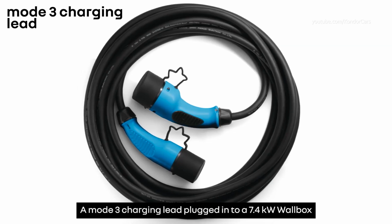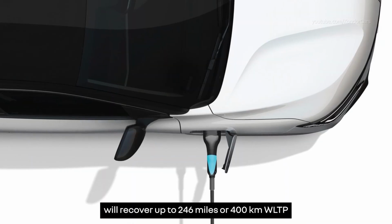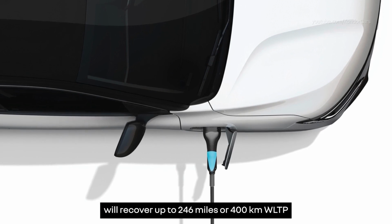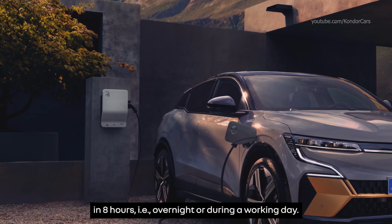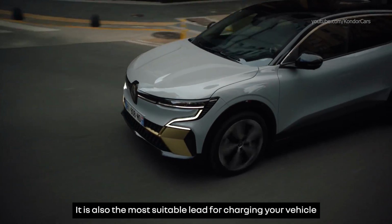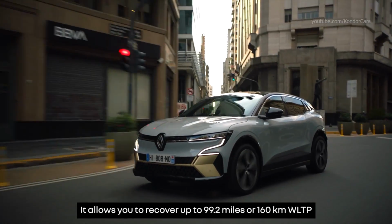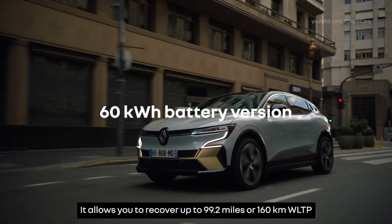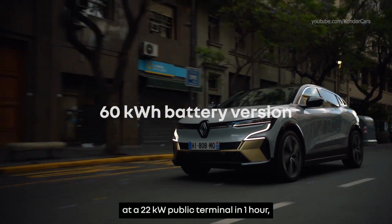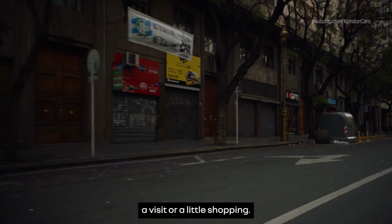A Mode 3 charging lead plugged into a 7.4 kilowatt wall box will recover up to 246 miles or 400 kilometers WLTP in 8 hours, i.e. overnight or during a working day. It's also the most suitable lead for charging your vehicle in a public space. It allows you to recover up to 99.2 miles or 160 kilometers WLTP at a 22 kilowatt public terminal in 1 hour, the amount of time needed for a meeting, a visit, or a little shopping.